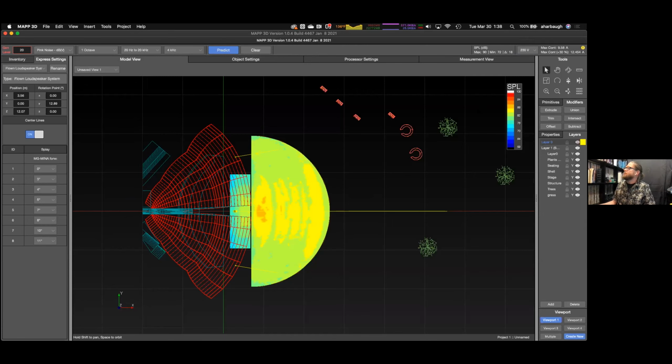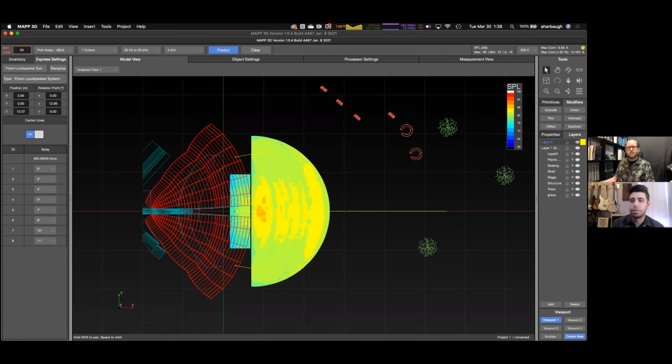Does changing the voltage, the operating voltage of the speaker, affect the SPL prediction at all? Nope. Nearly all of our loudspeakers can accept 100 volts to, I think it's 250 volts, but it might be 230. But yeah, they have switching mode, so that does not affect the performance of the loudspeaker. And so changing voltages should not change any prediction. It's really just that electrical consumption calculation.